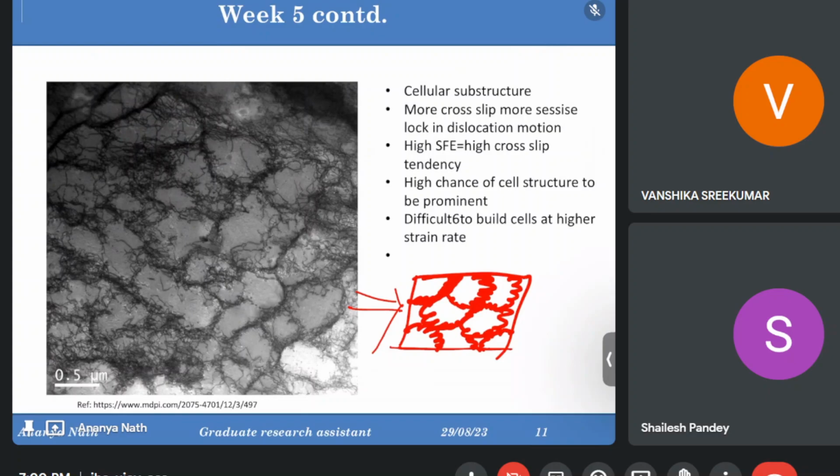When we apply cold working, deformation happens inside the material, but at the same time we are hardening the material. You can think of it like this: in cold working we are stretching the material, so we are increasing the length, or there is a lot of percentage elongation, which shows the ductility of a particular material, but still we are hardening the material.